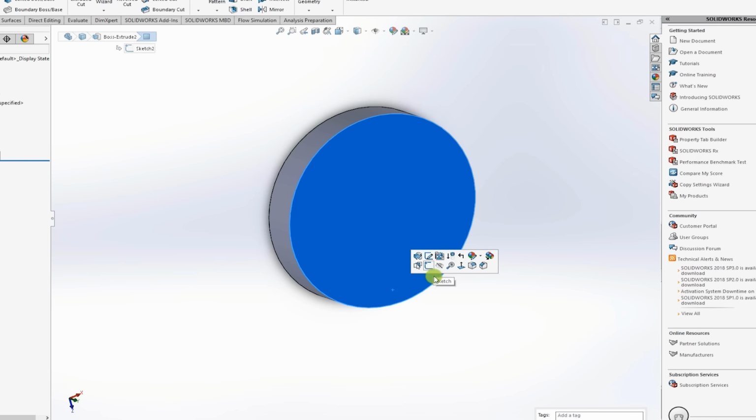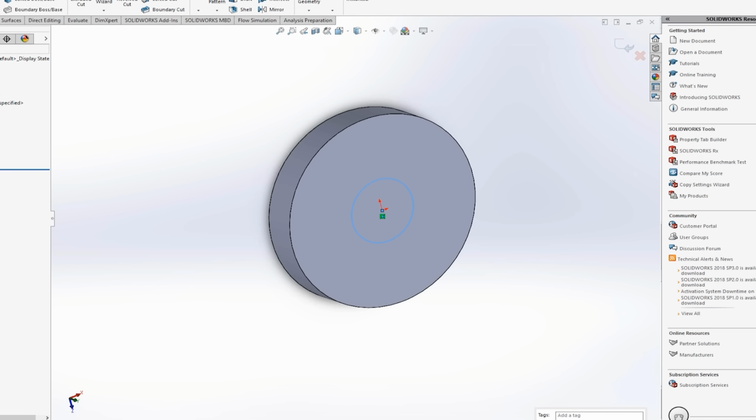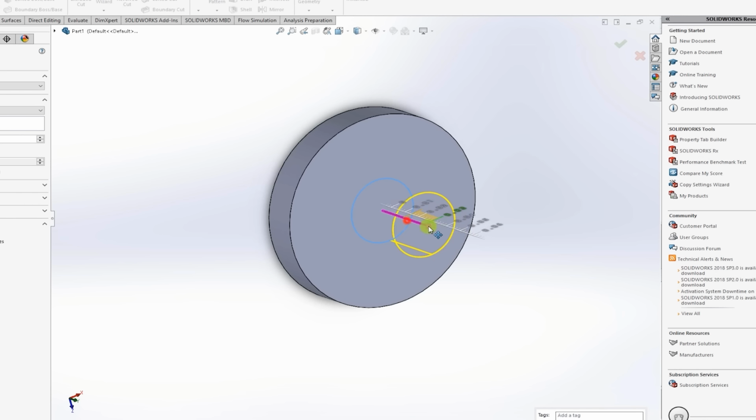Okay, alright, so this is our volute, and what I'm going to do next is I'm just going to draw a casing on top, and then I'm going to draw the inlet runner on the top. So let's create a circle, and we're going to type in 0.015 for radius, so that's about 1.5 centimeters, and this is going to be our inlet runner. Okay, in other words, this is the entry length, and we're just going to say that this is about 7 centimeters long, and type OK.